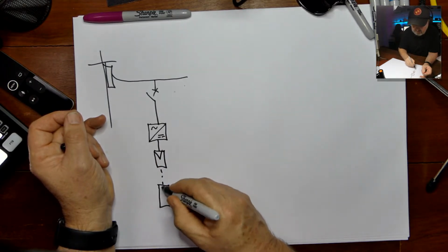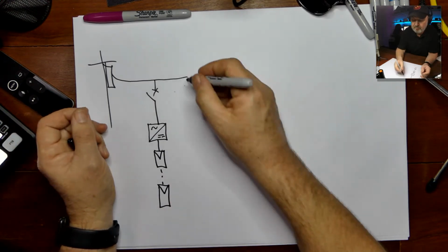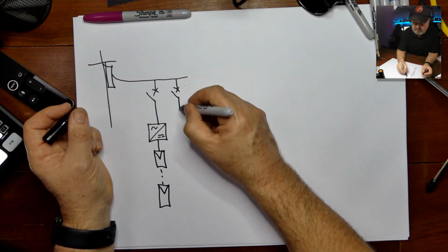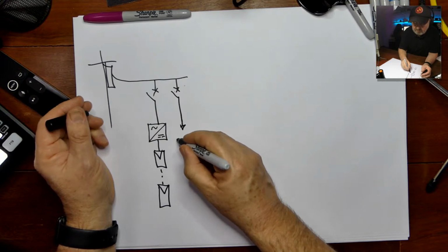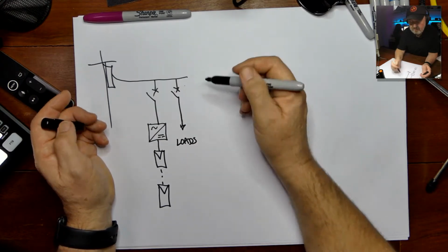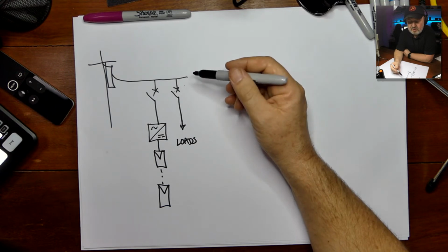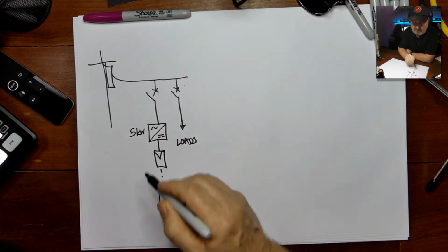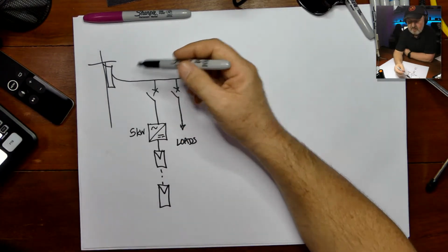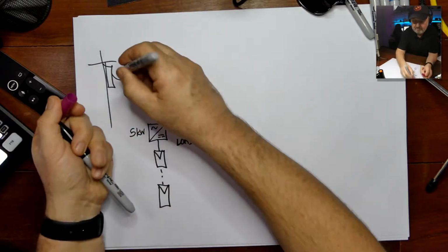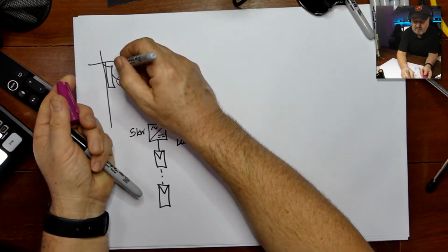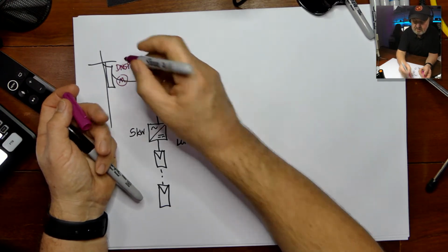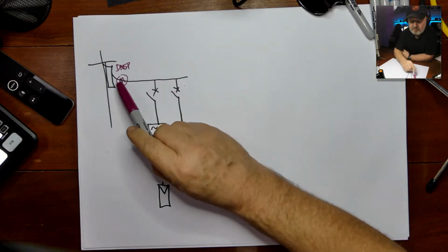Now you've already got this, so we're going to call this a retrofit solution. The customer already has solar, and it's exporting to the grid when they're not using it themselves. Here we've got the loads in our home. That's our basic installation of a grid-connect system. Let's say we've got a 5 kilowatt inverter here, and we've got a meter. That's actually quite important. This is the utility meter, or more technically, the meter installed by the Distributed Network Service Provider, DNSP. That's their meter, so that's what you get billed for.